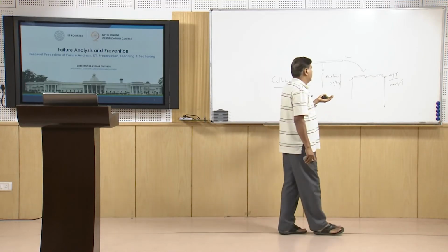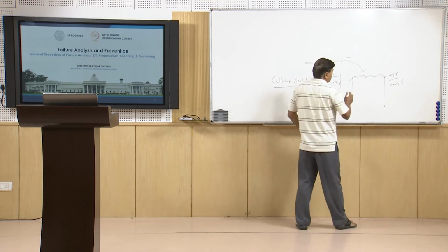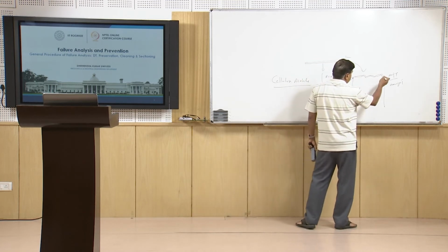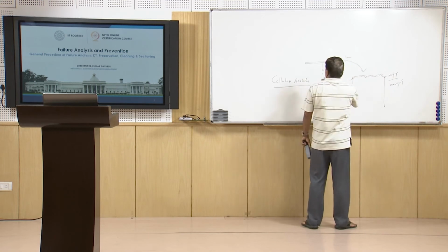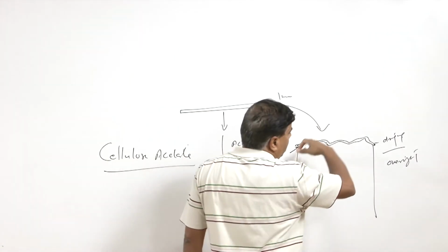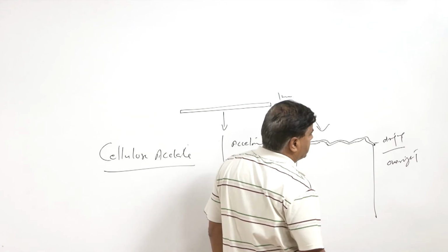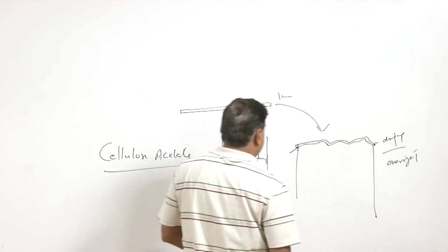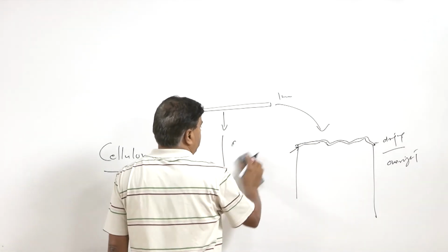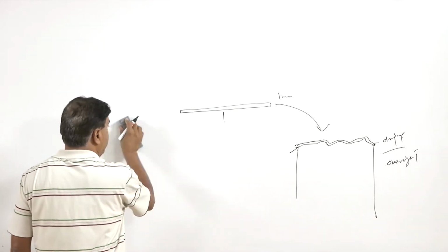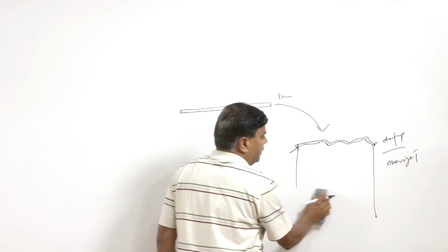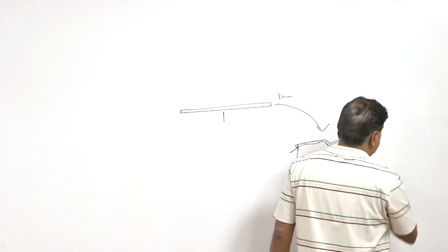So, the sheet morphology indicates the shape achieved by the cellulose acetate sheet, which follows the path of the fracture surface. It maintains a record of the surface morphology of the fracture surface, which can be used for interpretation in the failure analysis subsequently.